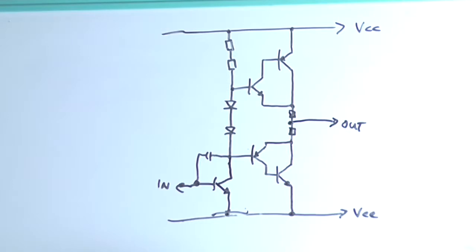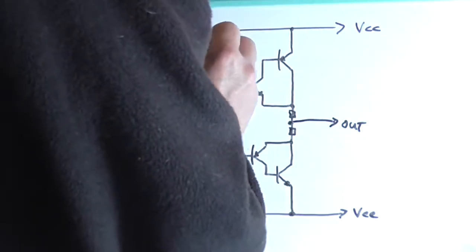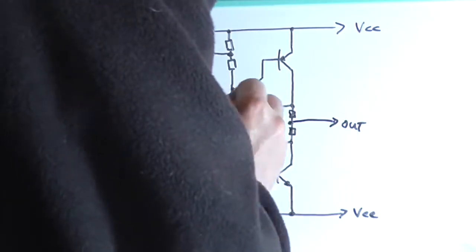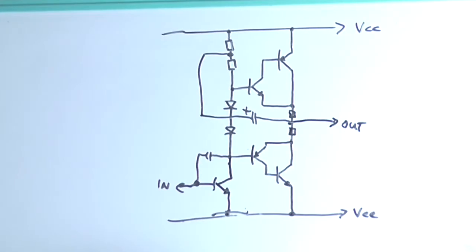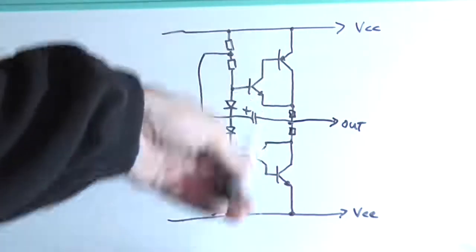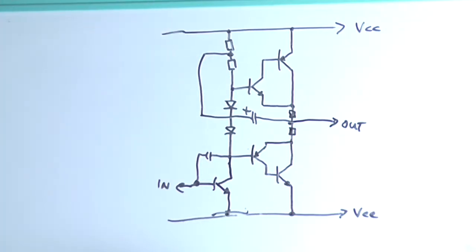So why have I got these two fixed resistors? Well, we can also do something known as bootstrapping. We can take an electrolytic capacitor between those two points, which now becomes a voltage divider, and connect it to the output. And what that does is it gives the output stage, or at least the drivers anyway, a constant current source in simplicity terms.